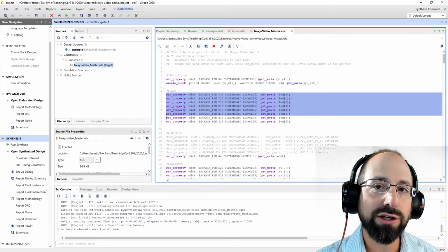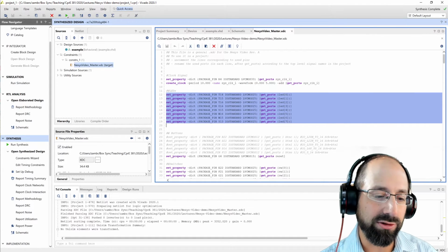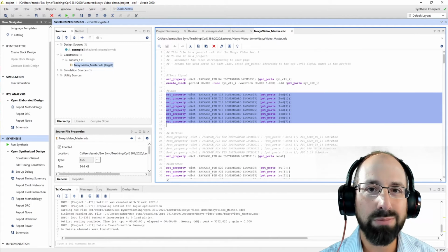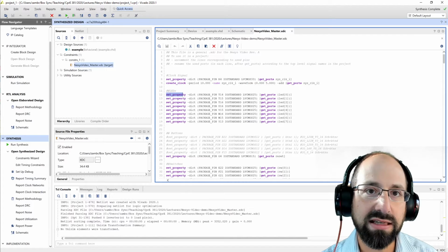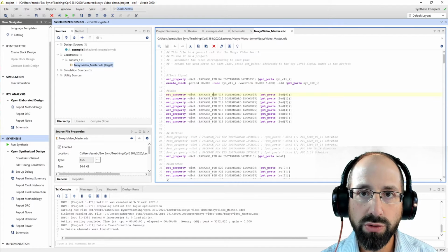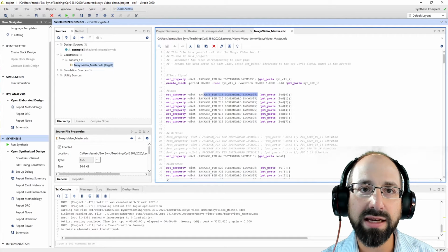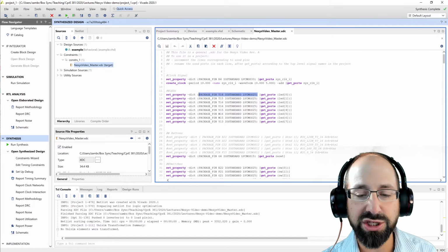Generally, the manufacturer for the board would provide you this file. It would also provide you the 300-page data sheet where you can reverse engineer where things are going to go. But the syntax for this can be a little bit ugly. So the only example I think I'll show you here is, and it's using that Tcl script just like everything else here: find a port named LED of bit 0 and set the property of that port that it needs to go on pin name T14 on this particular FPGA.